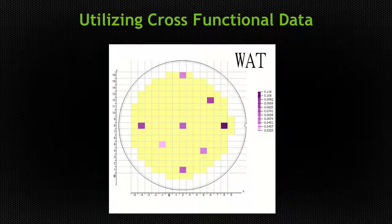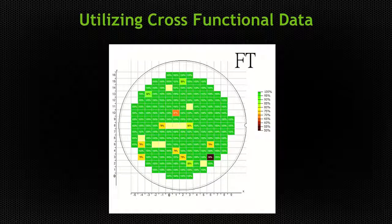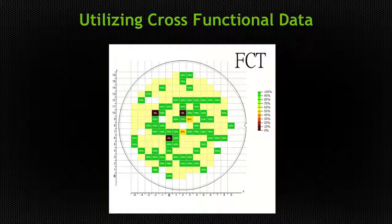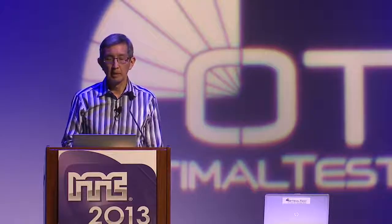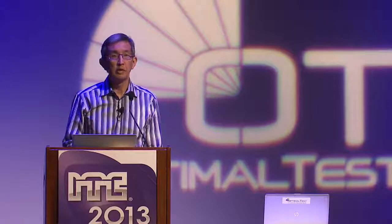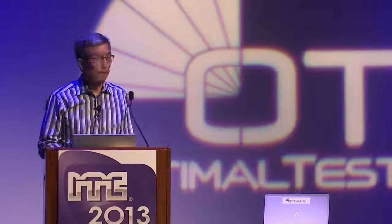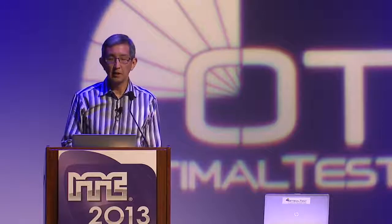One of the really powerful capabilities of OptimalTest is the ability to view cross-operational data. So what you're seeing behind me on the screen is an animation of a stacked wafer map of a fab lot as it goes through each of the different test operations in the manufacturing test flow. So this opens up so many different possibilities for yield and quality improvement. Normalizing to a wafer view in your cross-operational analysis, you can see that failures correlate to things like wafer location,